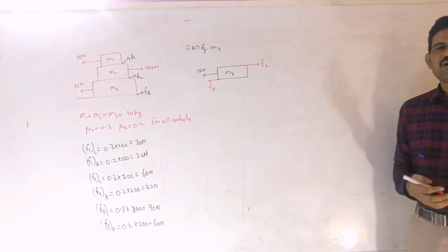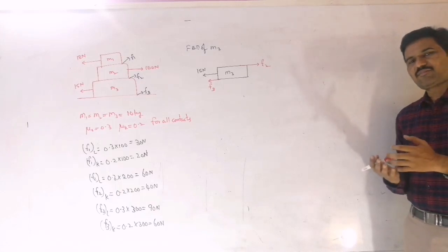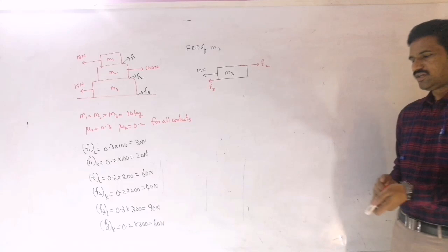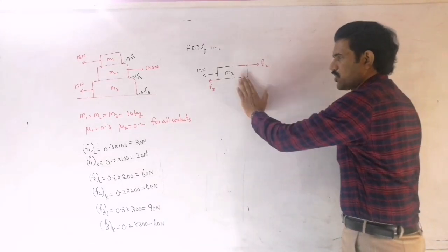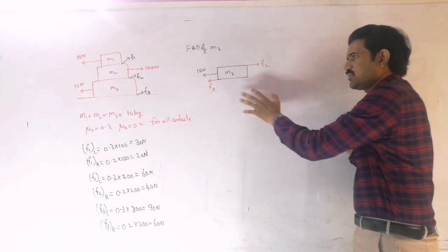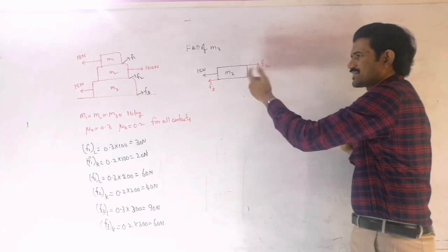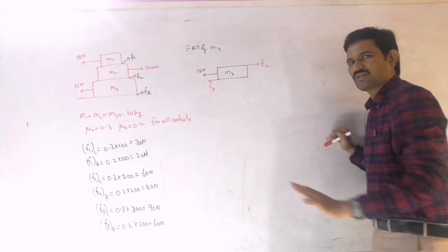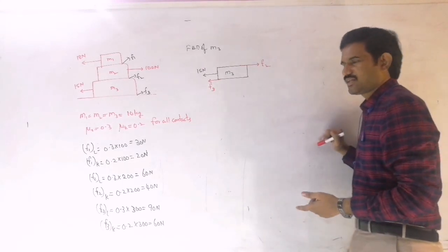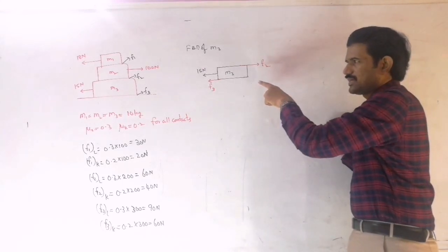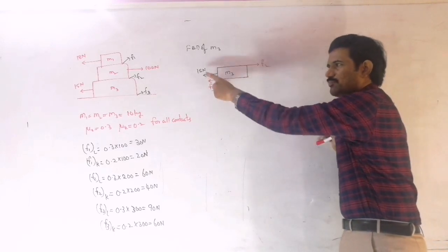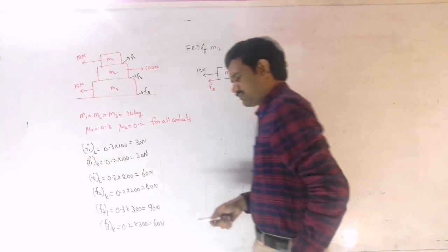In the two block problem case also, we discussed some problems when friction is there at the bottom. So now here the acceleration or the movement of this block is possible when this F2 value is greater than F3 limiting, if this 15 is not there, for example. Now as the 15 is acting, to displace this M3, F2 value should be greater than F3 limiting plus 15. Is it clear?